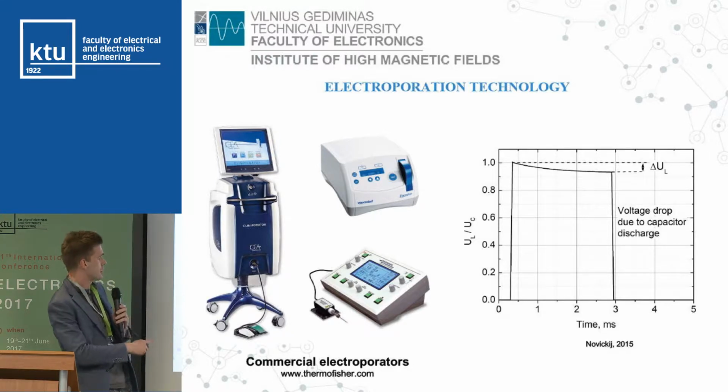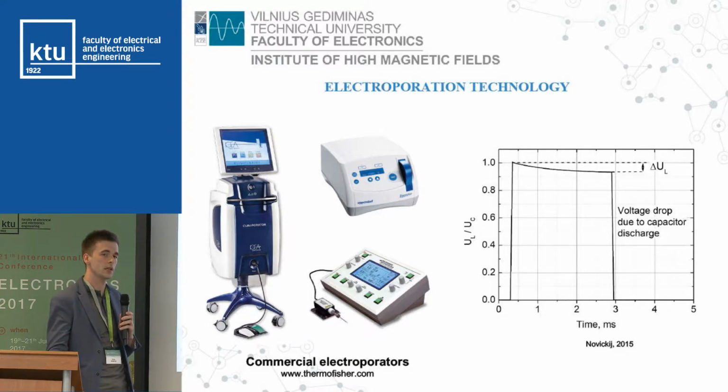These are commercial devices like electroporators that could be applied in both clinical research and in the laboratory, and usually you need some kind of electrical pulse. With pulsed magnetic fields, we try to copy this methodology. Therefore, we need to generate a pulse that is well controlled. You could control the pulse duration, the pulse amplitude, the number and frequency of pulses, and as a result, observe the biological effects, both in living microorganisms or in vitro, like you have a cuvette, some kind of sample, and just laboratory research.